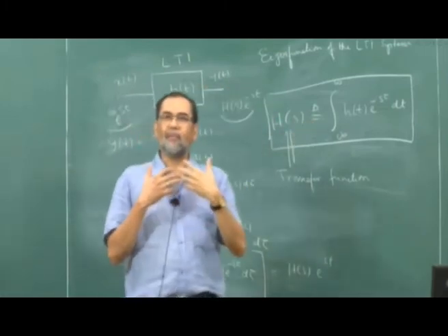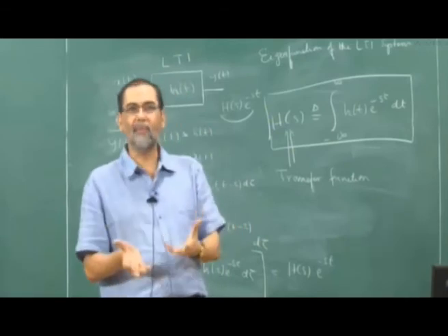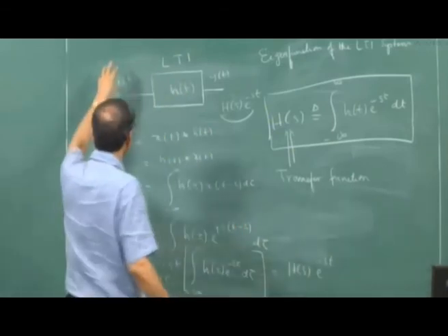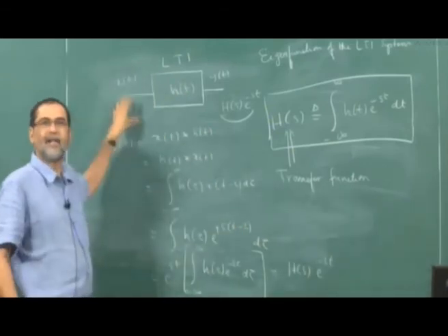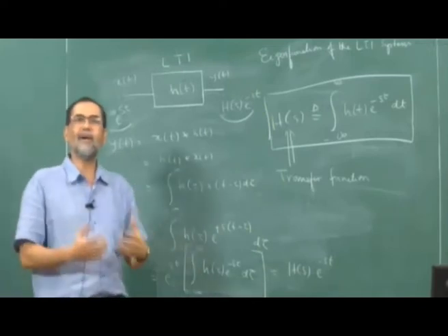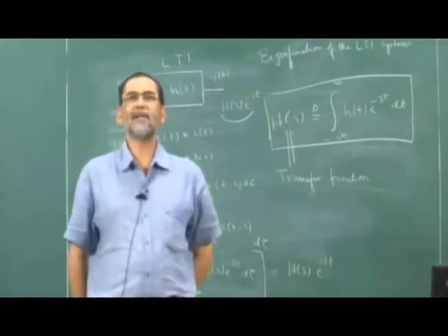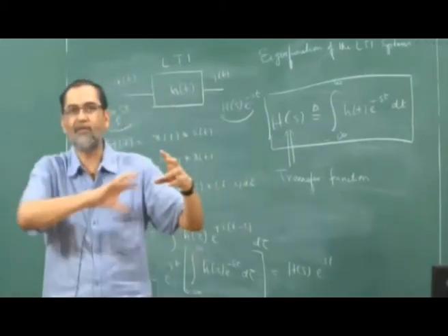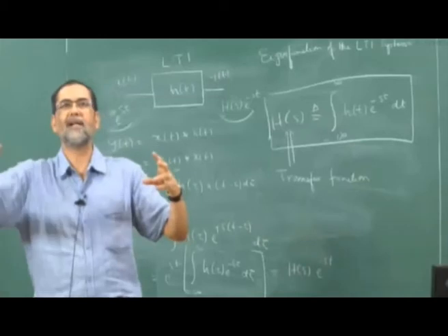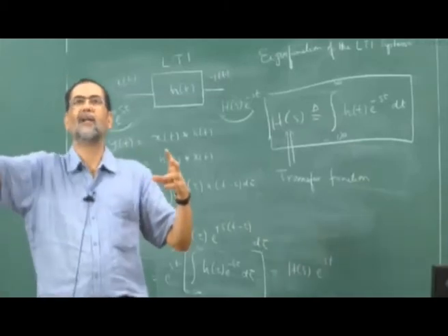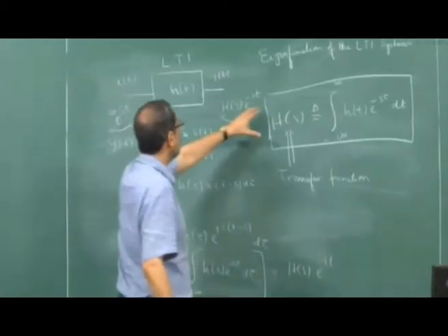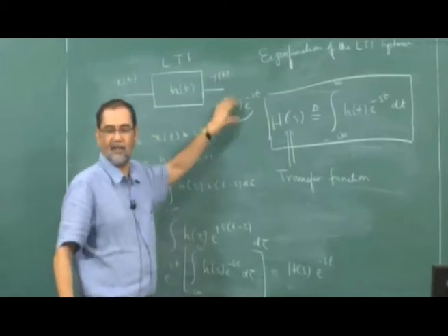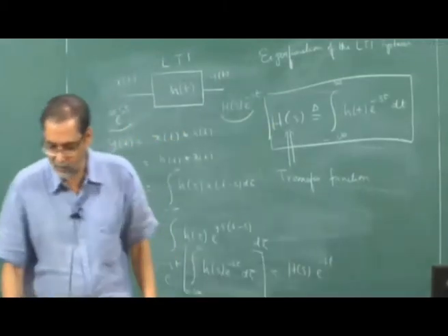The reason I want to go into the frequency domain is I want to express my input signal in terms of its frequencies, because the moment I express my input signal in terms of its frequencies, I can take individual frequencies and give them to the input, and I can predict the output will be the same frequency with some different scaling factor.